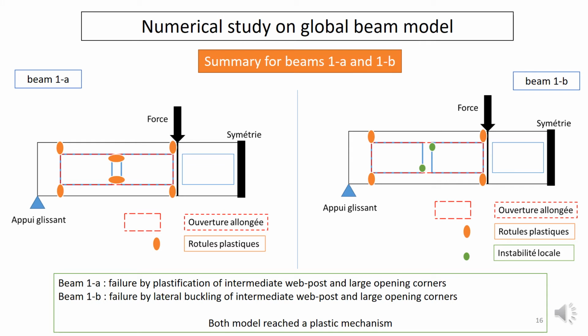This phenomenon could be observed for both cases, and in both cases we had either plastification of the web post or lateral buckling of the web post, and both reached a plastic mechanism in the enlarged opening.